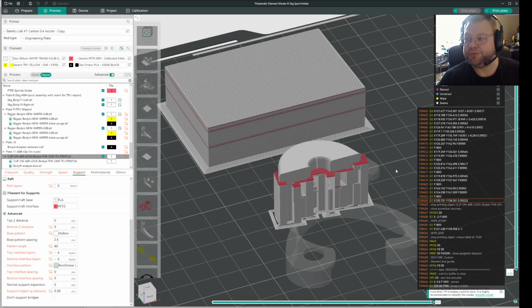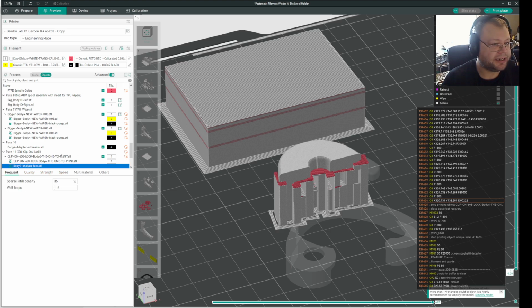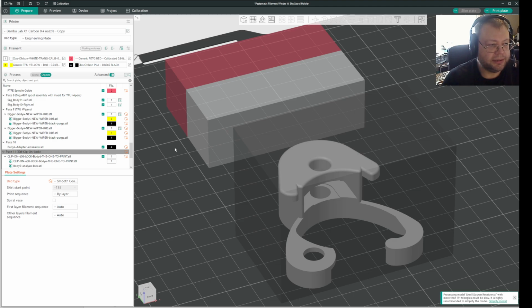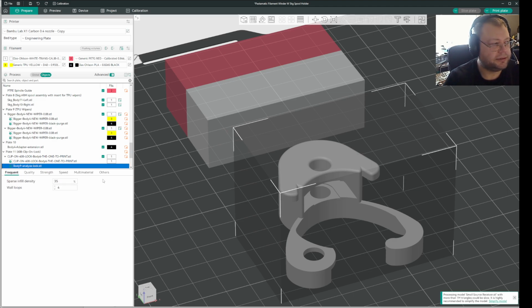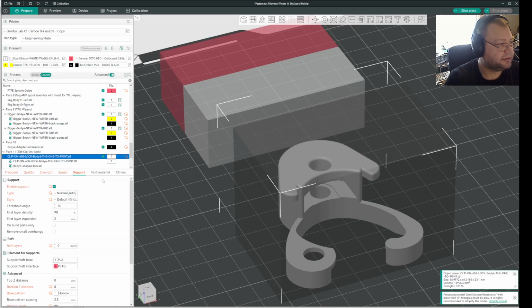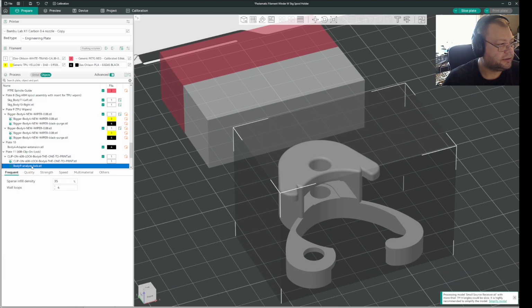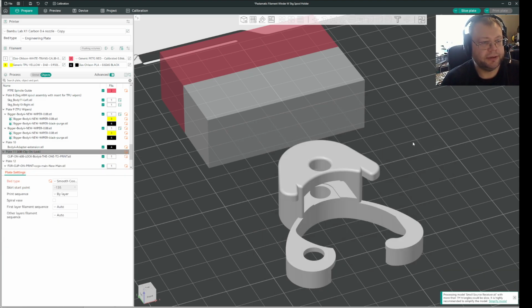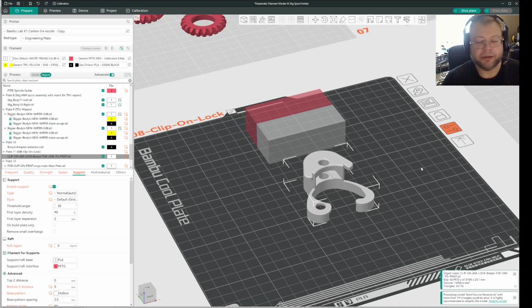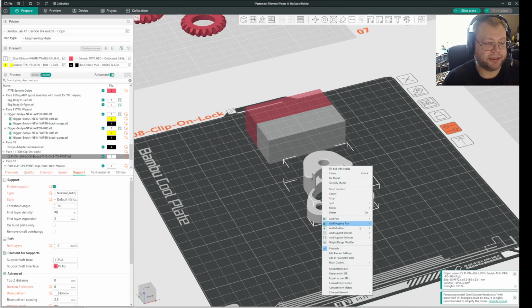Now that was made from my beginner level perspective, and I was kind of proud of figuring that out, but I found out how to do this directly in the slicer, and it's actually easier, and I do recommend the new way. So let's go back from that. I'm going to delete the analyze block there. So remove that. What you can do is mark the object you want to analyze, and then right click and select add negative part, and use any of the objects you have here.